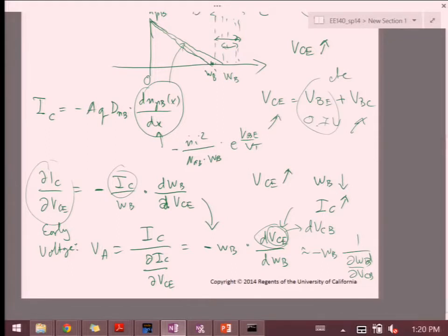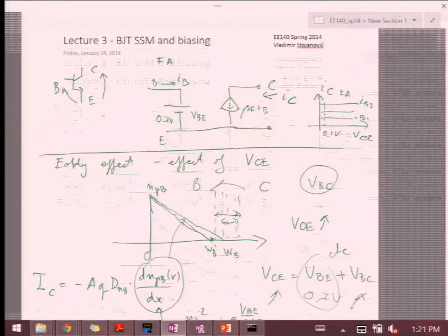And that's exactly what this factor is here. The width of the depletion junction will depend on the doping. So if you plug the dopings in, typical for the collector and base, what you're going to see is that this VA is typically about 15 to 100 volts for the NPN transistors. Okay.